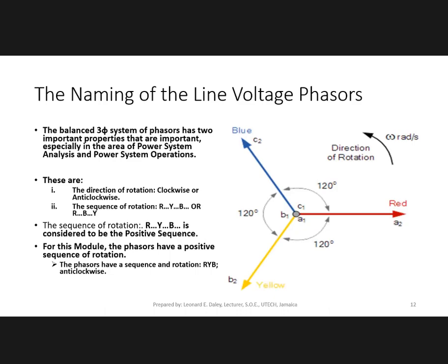If you change around two terminals of say a motor, let's say it was rotating in the clockwise direction before, and you switch around any two terminals, you will find that the motor will actually start to turn in the anti-clockwise direction.